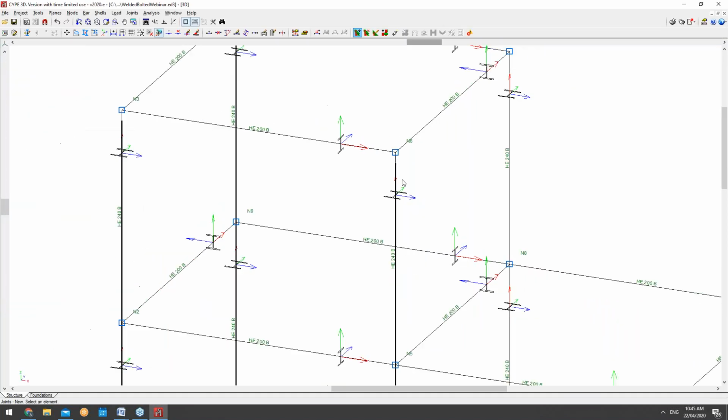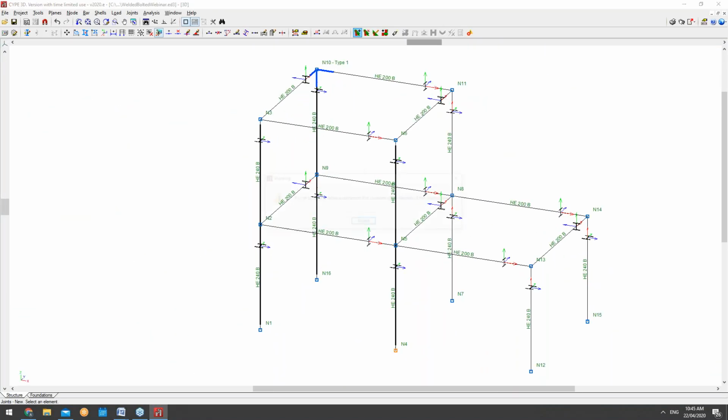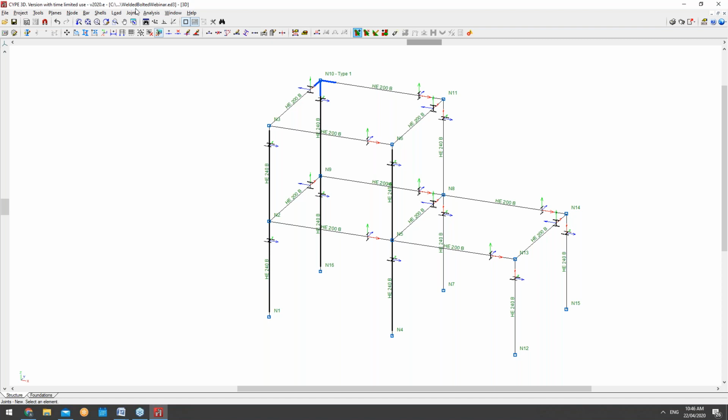Now let's save the change. Now what I can do as well is let's have a look at the capabilities on the whole. We can come over here to joints. Instead of generating each one, I can of course generate them all together. But before we do that, you can see here that I can assign and group certain welds as well. So what this basically means is when we're dealing with material schedules as well, that same grouping is defined in those reports as well. So we can basically condense our views quite nicely.